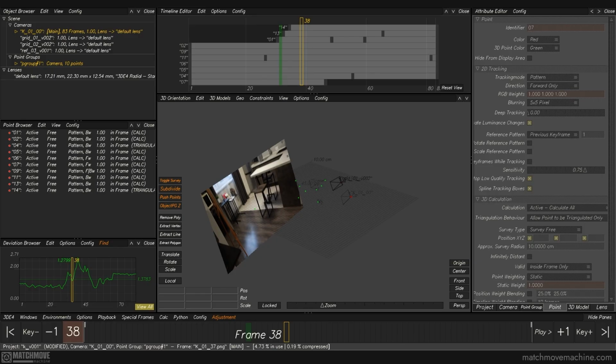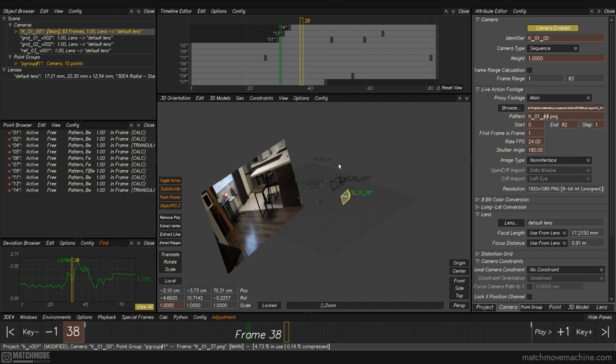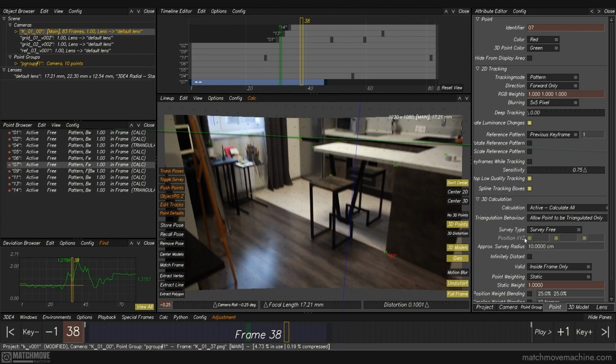There's another way to set scale and orientation, specifying the actual coordinates of the points. That's more accurate because those coordinates take part in the camera solving process itself rather than placing the scene on top of an already finished solve. So let's say I know this point's coordinates and I want it to be at the origin.